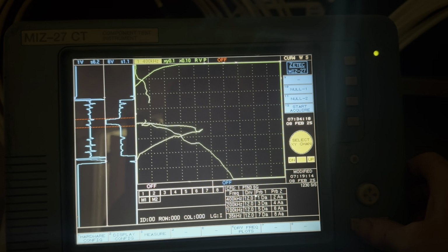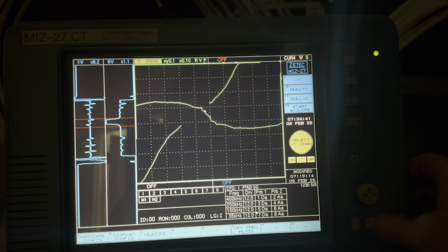They're meant for a purpose to hold the tubes in place, but they can also cause problems like wear fretting in the tube from rubbing against the tube wall. That being said, a tube support plate's a big piece of metal. It's conductive, and it will affect the eddy currents caused by your coil a lot. So for channel 7 and 8, we usually set the TSP, or the tube support plate signal. And how we would set that is like this.